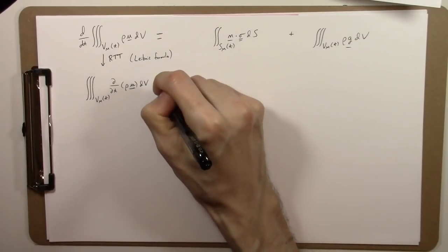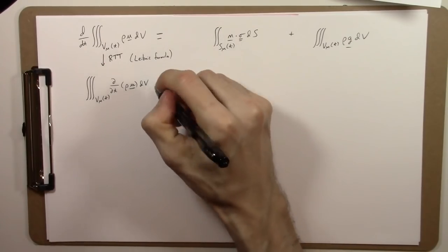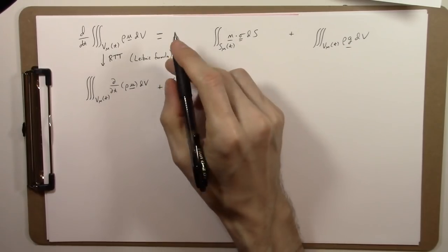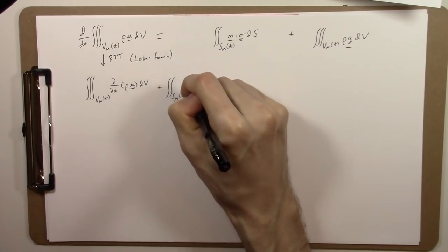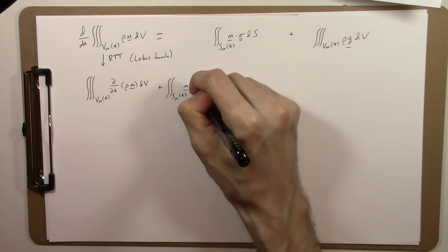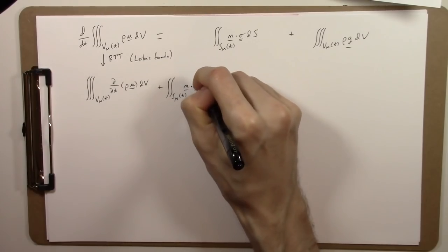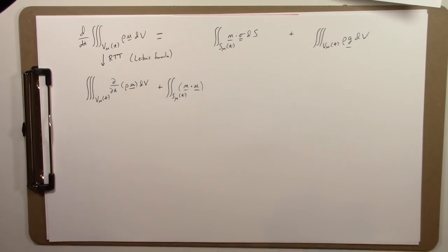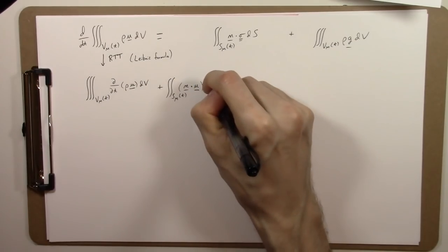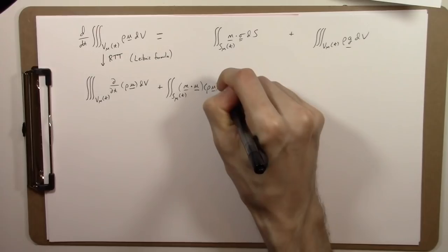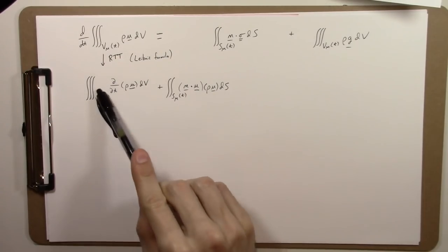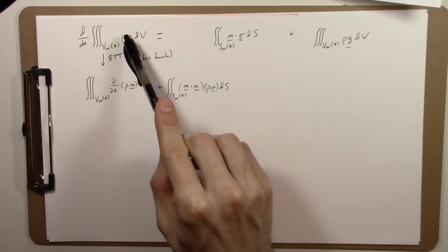So the second component here is plus the surface integral of n dotted with the velocity of the control surface, which is Vs, but Vs is just equal to u, the fluid velocity, since it's a material control volume. So n dot u, and then we keep the integrand rho u, dS. So the first term takes into account the time dependence of the integrand itself, the momentum density rho u.